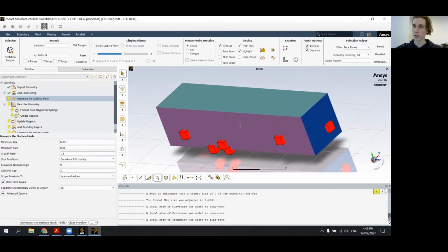And remember, the smaller you make your mesh, the slower it's going to be to get results. If you want to keep solving for different iterations of your design, that can get really important. You want to minimize the time that your computer has to spend calculating this stuff, so you really want to create the largest mesh that you can while reasonably capturing the physics of what's going on